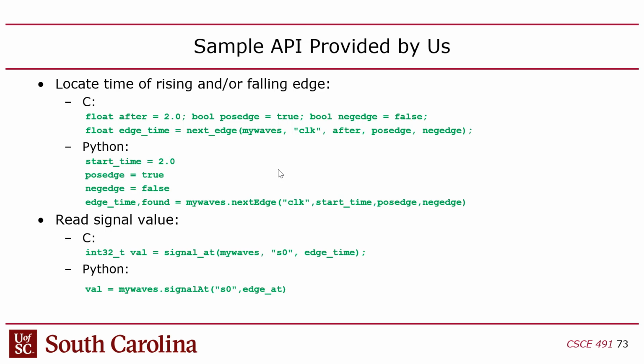So what you're going to be looking for is, initially, the falling edge of slave select, and then you're looking for either the rising or falling edge of clock, depending on how the channel is set up. And then at each one of those falling or rising edges of the clock, you look at the corresponding value of MISO and MOSI. Make sense? That's basically the idea.